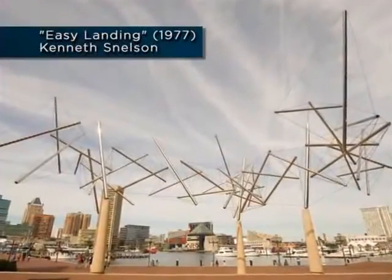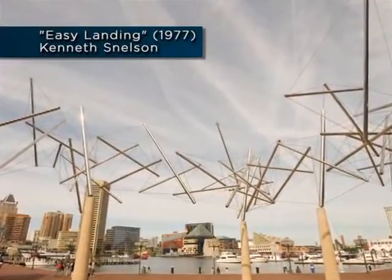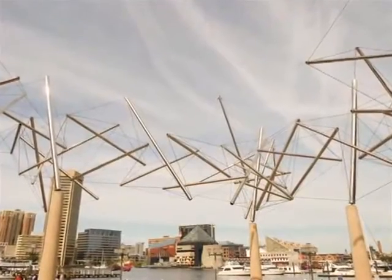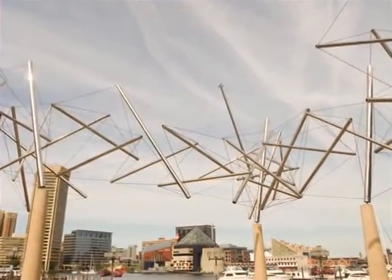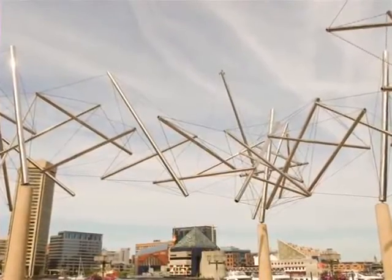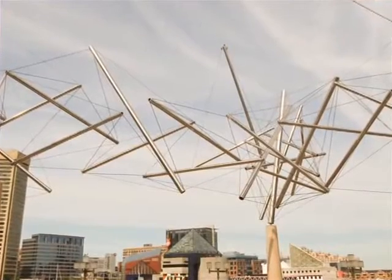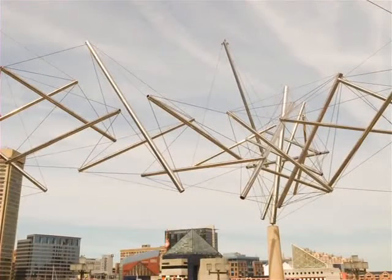The cable dome is an ingenious structural system that exploits a concept called tensegrity, which was first proposed by Buckminster Fuller, the inventor of the geodesic dome. Tensegrity has been the basis for some really interesting modern sculpture, like the work of Kenneth Snelson, shown here. A tensegrity sculpture is an arrangement of very slender tension members, wires or cables, and a smaller number of compression struts, with no two compression struts ever touching each other. Buckminster Fuller called these struts small islands of compression in a sea of tension.